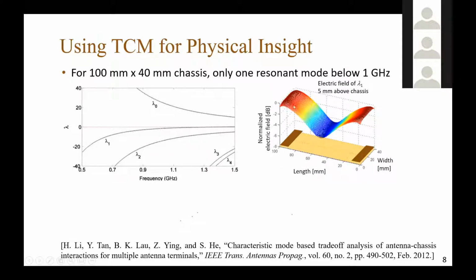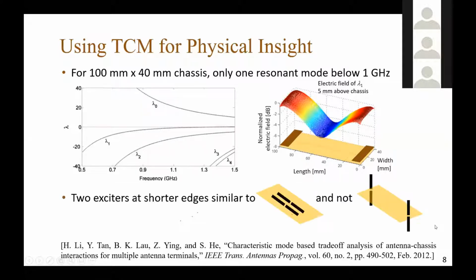By using this antenna, we excite the chassis with its fundamental mode, and the second antenna excites the chassis with the same mode. So they will couple to each other like crazy because we are exciting effectively the same mode. The reason we do not couple completely is that we often excite some other modes to a lesser extent.